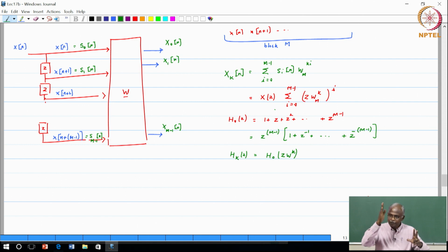You get the filters in the correct sequence. You replace the transpose conjugate of the DFT matrix with the DFT matrix, and you get the same outputs, but the output sequence is scrambled. Now, if you keep the DFT matrix the same but change the delay chain into the advance chain, then what do you get? The sequence comes out again in the correct form.